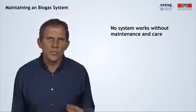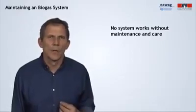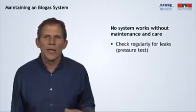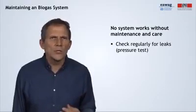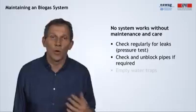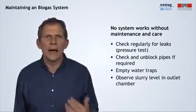Remember, no system works without maintenance and care. What does that mean for a biogas system? We need to regularly check for leaks. We can do this with a pressure test, looking if the gas pipes are okay. We also need to check and unblock pipes if required. We must not forget to empty water traps, and we need to regularly observe the slurry level in the outlet chamber.